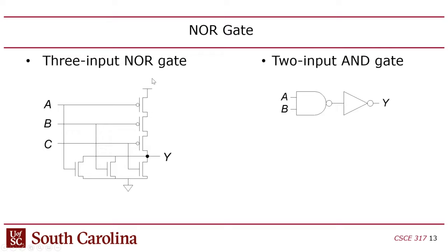In the case of a NOR gate, keep in mind, I'm not talking about an inverter here. In order for the contamination delay to not equal the propagation delay, first of all, you have to accept the fact we're not talking about an inverter. Inverters probably won't have a difference between propagation and contamination.